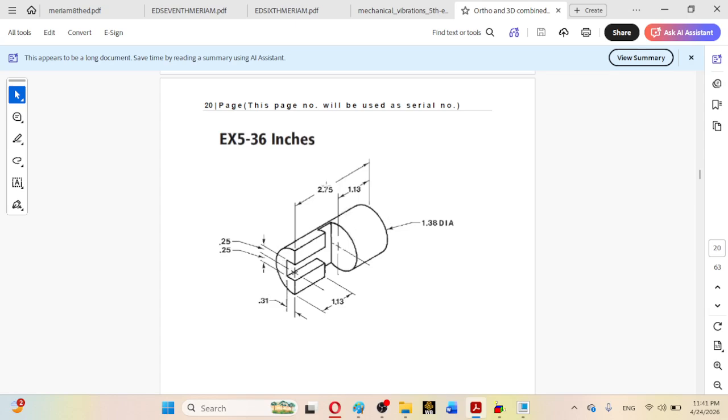Both commands can be equally applied, but the revolve command must be used where it is imminent, or where no other command, meaning the extrude command, can work. Here the extrude command can work successfully. For example, you can just create this circular face on the front plane, and after that you can also create this sketch on this face, and then you can make a cutout like this.